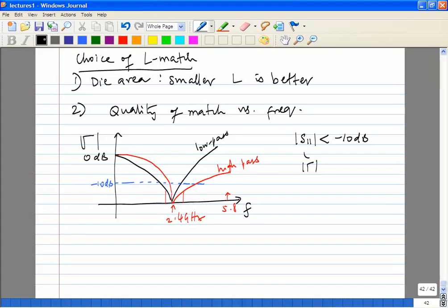Now the third thing is parasitics. For example, you're trying to drive something off chip. That's what we've been looking at. I don't know how much you know about IC technology, but coming out of the IC, you have the circuit, then you have what is called a bond wire. You put a pad, and you have a bond wire which goes from the pad to the external lead. So all those things add inductive parasitics.